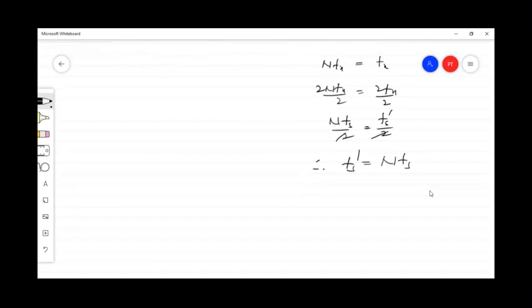When you want to compare a delta modulation system and a PCM system based on signal to noise ratio, you must assume that bandwidths are equal. The bandwidths are equal if the sampling rate of the DM system is n times the sampling rate of the PCM system.